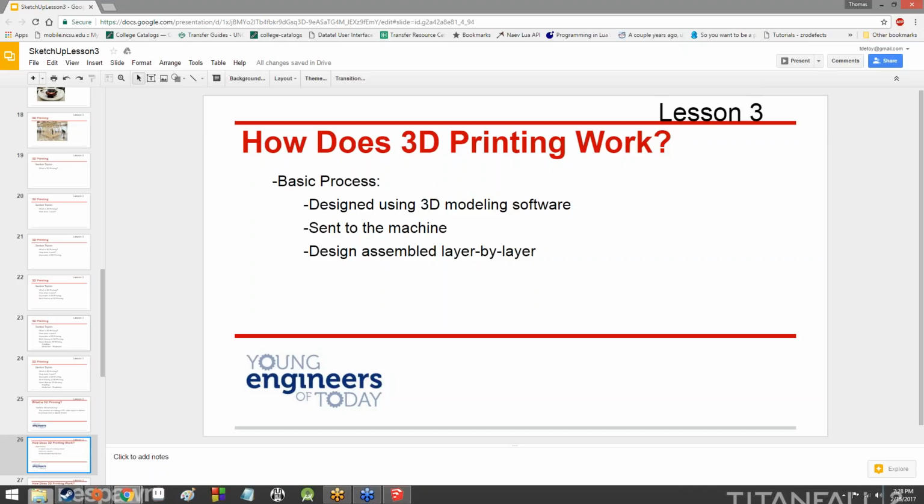It squirts out some plastic in the shape that it needs to, and then it moves up a very, very tiny fraction of an inch, and then it works on the next layer, replicates it, and then the next layer, and the next layer. So if you ever look at 3D printed stuff, generally a lot of stuff done with modern commercial 3D printers, especially if it's a very fast print, will be ridgy or bumpy. You'll notice that there are grooves all in one direction across the 3D model, and that's how you can tell how the 3D model was printed.